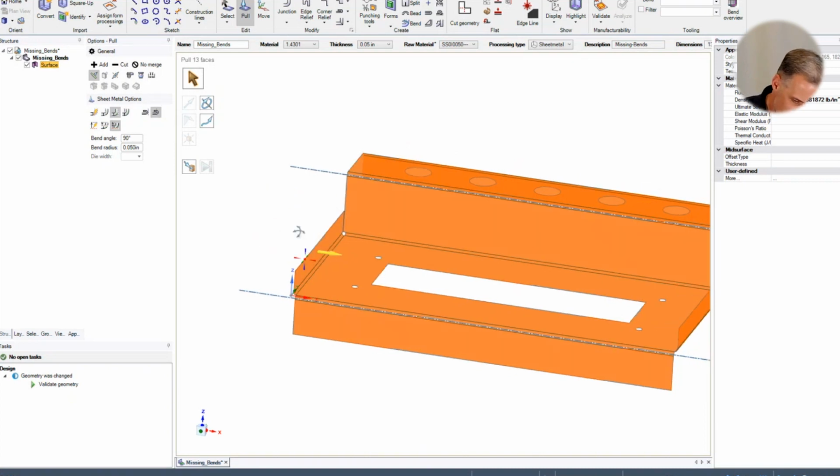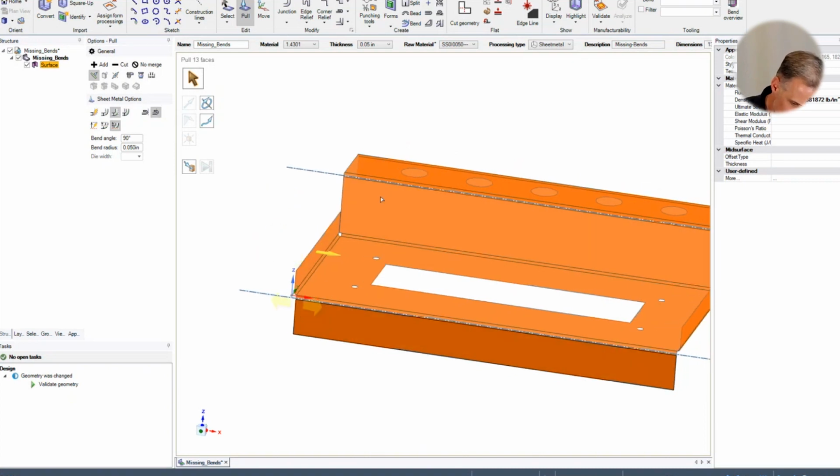And in our case, during the collecting of the inside face, I know now that I need to thicken up this face into the opposite direction. So in my case, I must thicken up this face in the minus direction.